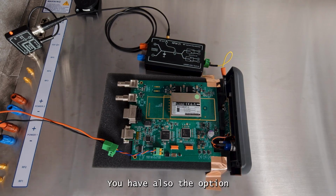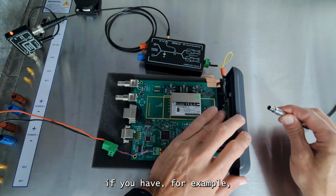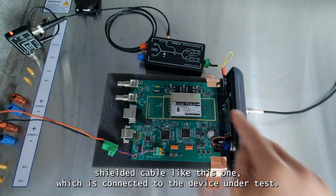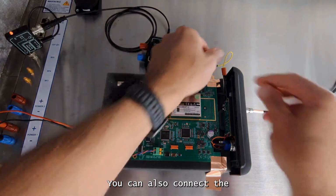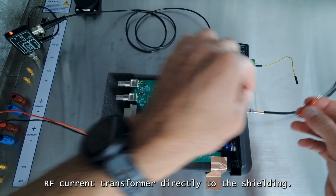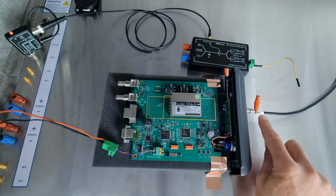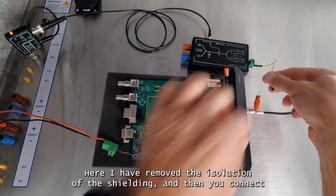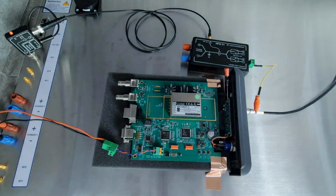You also have the option, if you have, for example, a shielded cable like this one, which is connected to the device under test, to connect the RF current transformer directly to the shielding. Here I removed the isolation of the shielding, and then you connect the current transformer to the shielding here.